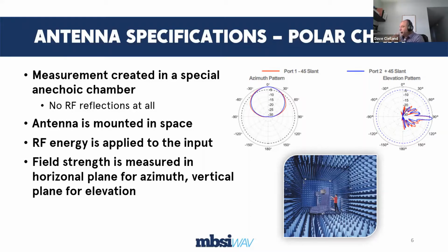And so if you want 3 degrees of electrical down tilt on an antenna, you dial up with a screwdriver or an Allen key, 3 degrees down tilt or 2 degrees up tilt, or whatever it is that the RF engineer is calling for that particular installation. In this particular case, we have a couple of degrees of down tilt that is built into the antenna.